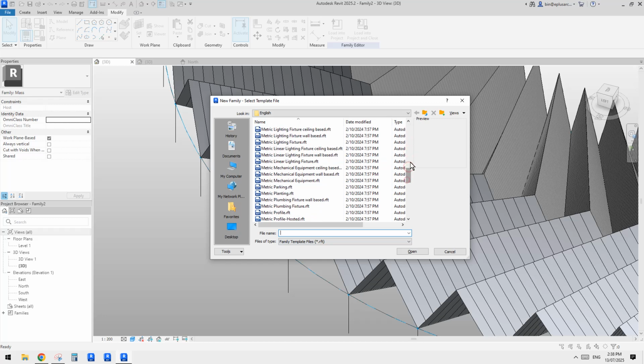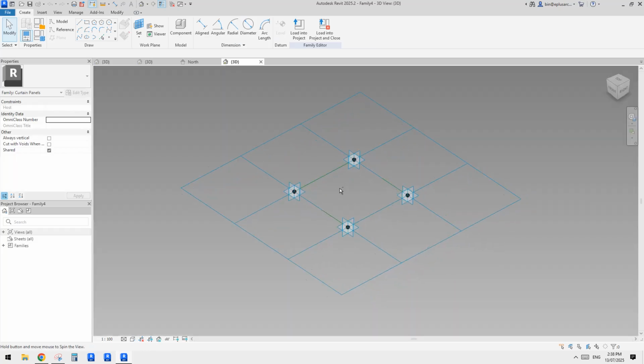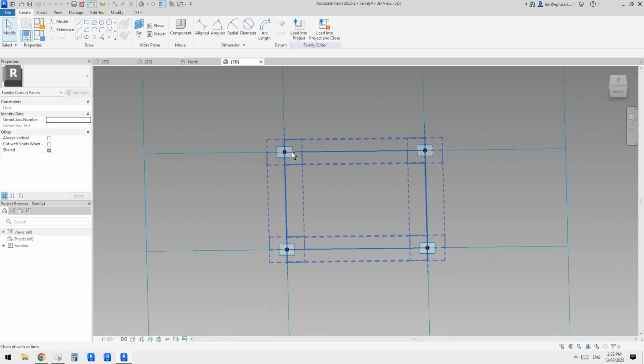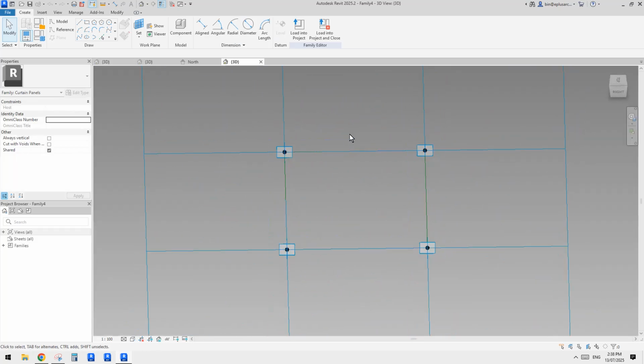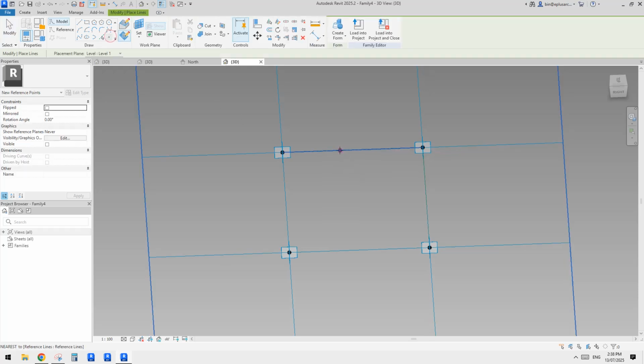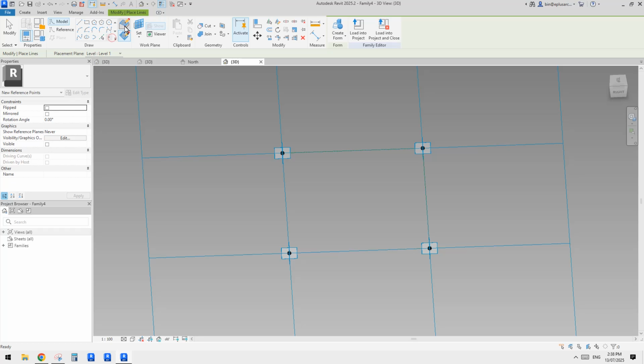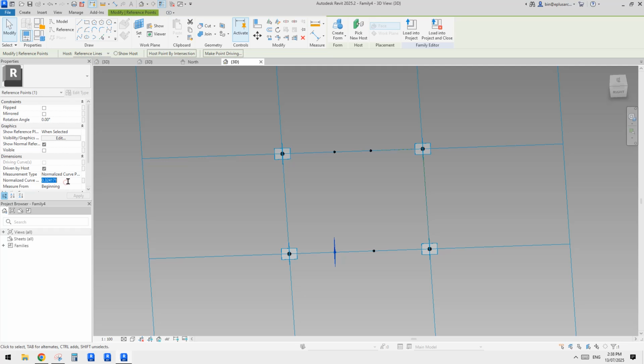So I'll just use generic model pattern-based, and basically we need something, a ridge here. So maybe I'll just place it in the middle. Maybe I'll just do this just roughly. I'll place one, so draw on face. Okay, make sure draw on face, and I'll just use 0.4 maybe.